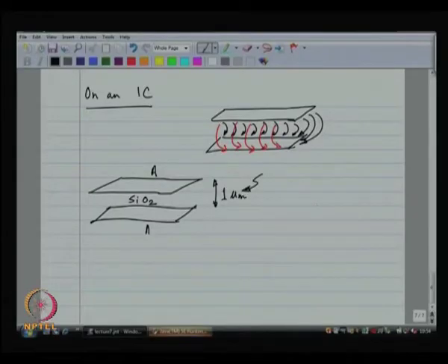Okay. Now, some of the modern processors offer some capacitors called MIM capacitors. These are special capacitors which are offered in the top metal layers, and they have a controlled distance, much lesser distance between the two plates.